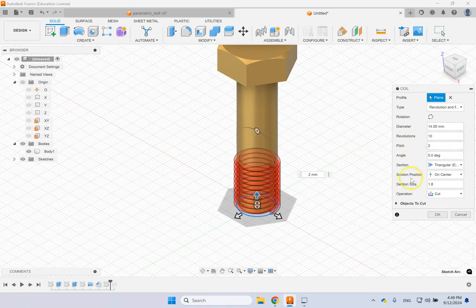Okay, so you have to know what is the size of the profile for cutting a specific thread. And the profile of the thread, when you cut it, is not perfectly triangular. The tips of the triangles are kind of cut. There is a chamfer there. And the roots of them have fillets.